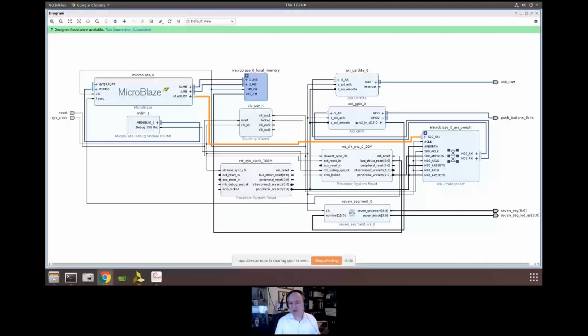I saw somebody asking if you could do this on the Snickerdoodle, and you can follow through and do all this on the Snickerdoodle. The one issue, obviously, is that if you've just got the SOM, it doesn't natively have a video output port. You would need something like the Snickerdoodle Pi Smasher to be able to connect an output, and in that case you'd be outputting over HDMI. But the concepts and the techniques I'm showing here can be used across everything else that we're going to see.